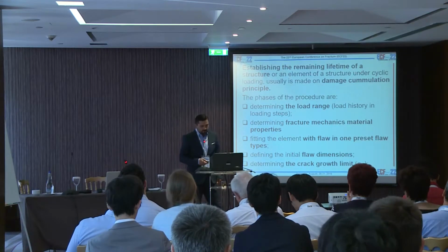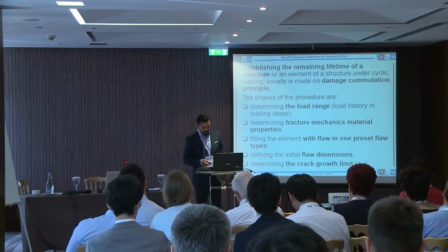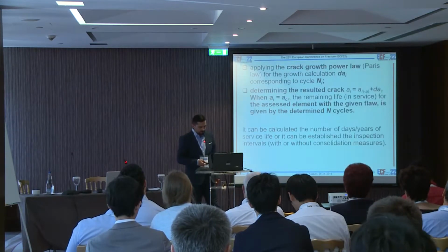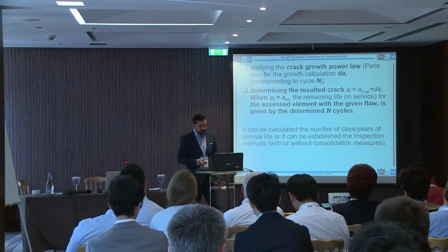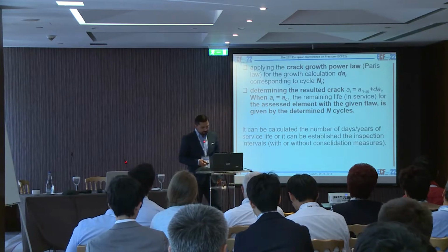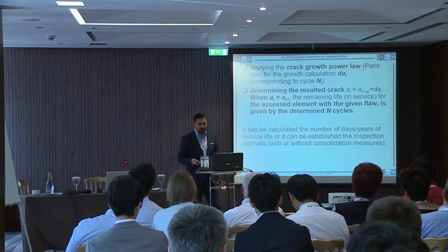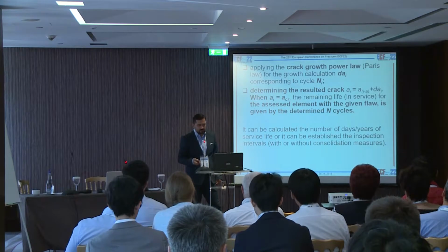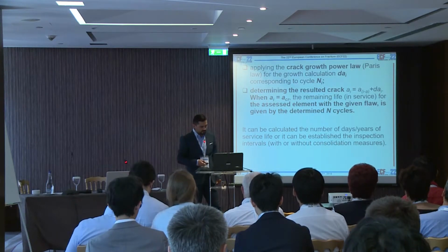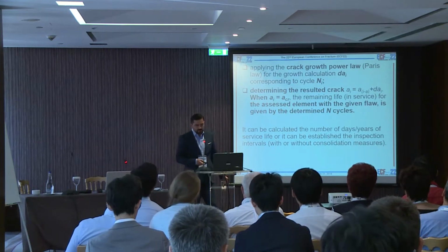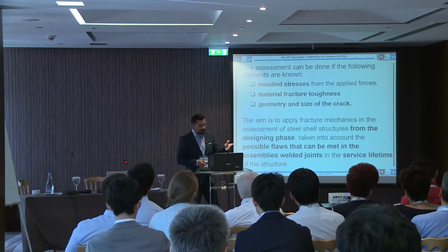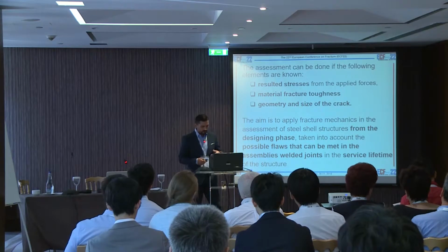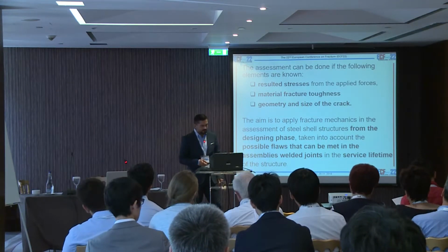Defining the crack growth limit, we will see what we can apply. We can apply a British standard here, and apply the crack-growth power law, the Paris law, and in the end determine the number of cycles for the crack to grow from the initial size to the critical crack size. In this way, of course, the number of days or years the structure can be in service until the failure of the element can be calculated.